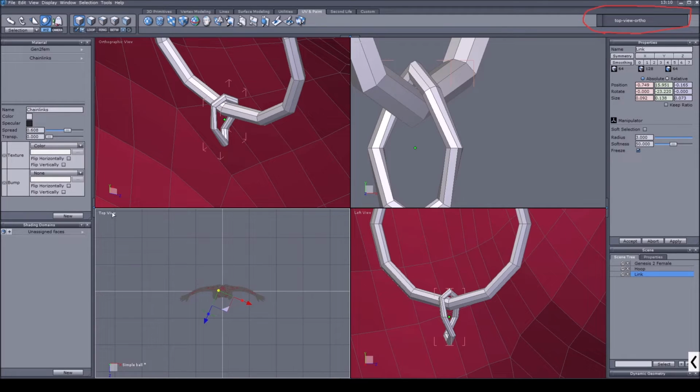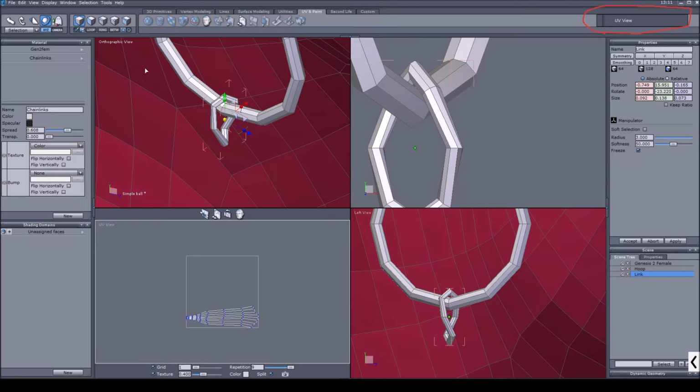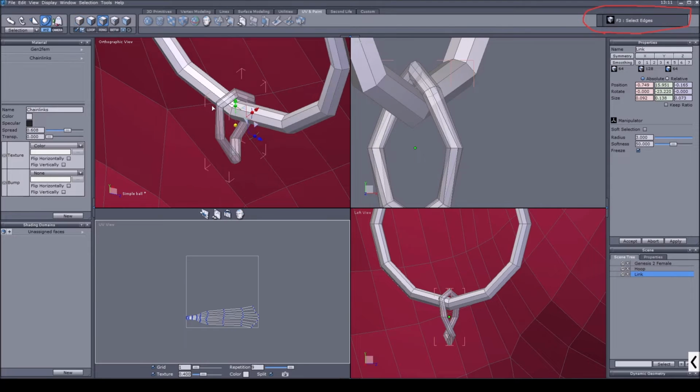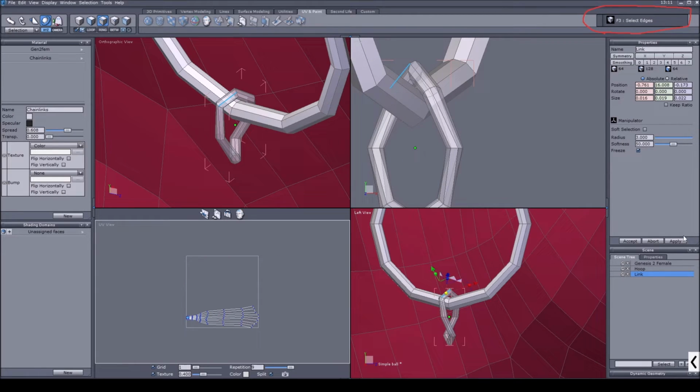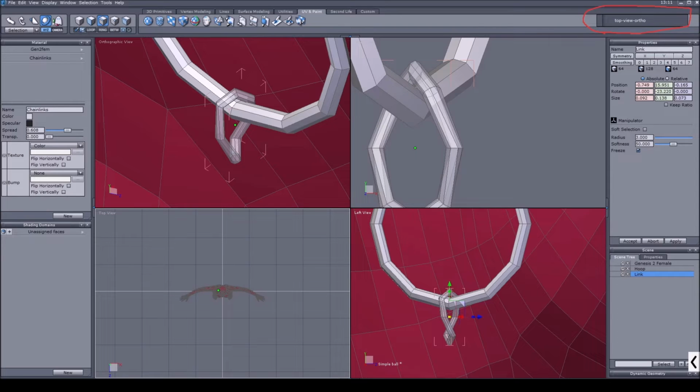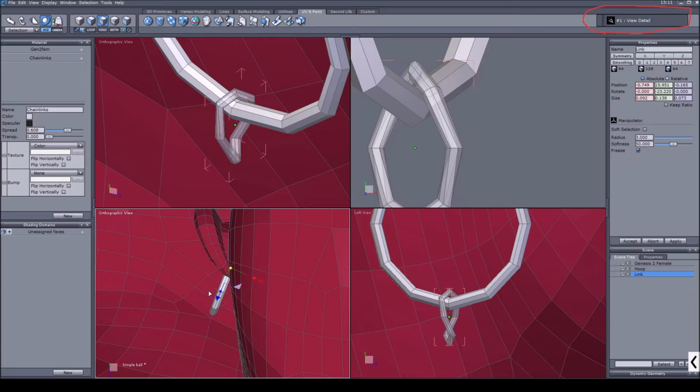Top. By the way, if you have the UV map open and, for example, you work on the detail of this, like you have something selected, and you go into the UV map, usually it unselects whatever you have selected. So sometimes having the UV map open can unselect your stuff. So if that happens, best is to go back to whatever you usually have in this viewport.